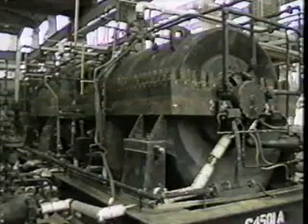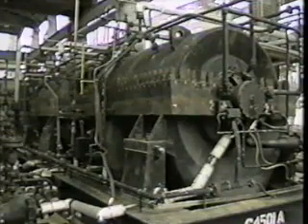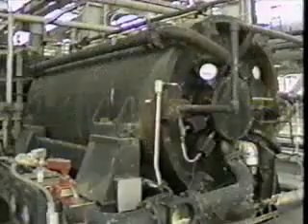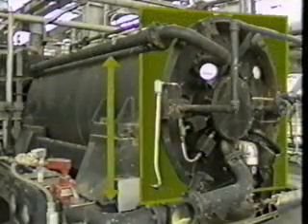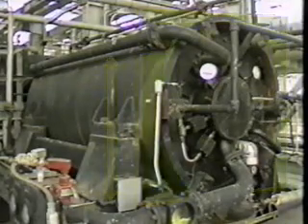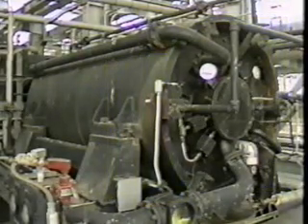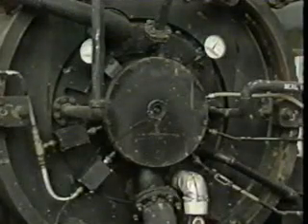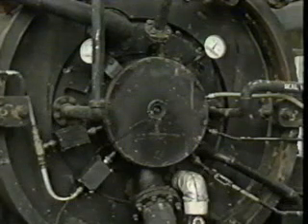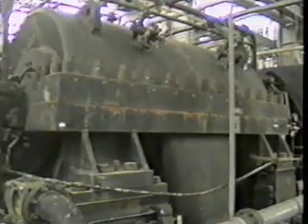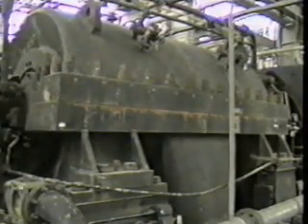In centrifugal compressors, there are two primary casing designs: horizontally split, otherwise known as axial, and vertically split, sometimes known as radial. This split in the casing provides a means for reaching the internal working components of the compressor for repair or replacement. In addition, the material used to make the casing is determined by factors such as stress, temperature, and corrosion.